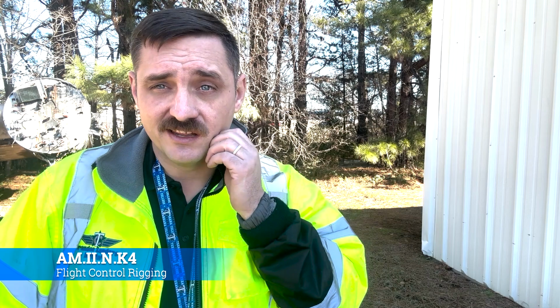What goes into that? And this is something that if you're a helicopter mechanic, especially if you're on the line, you'll end up spending a lot of time doing this, because helicopters naturally just want to fly apart. It's kind of an old adage that an airplane wants to fly and a helicopter wants to break. And so you'll spend a lot of your time doing your track and balance and rigging the flight controls to make sure that they stay exactly the way that they're supposed to, and that they don't get out of track or out of balance, and so forth. So let's talk about that.